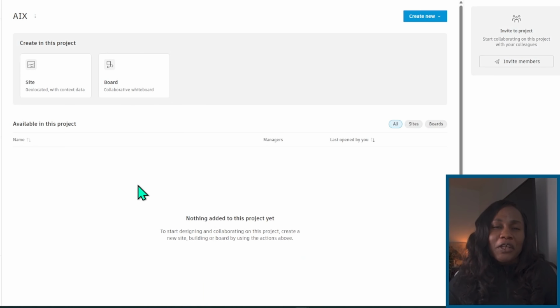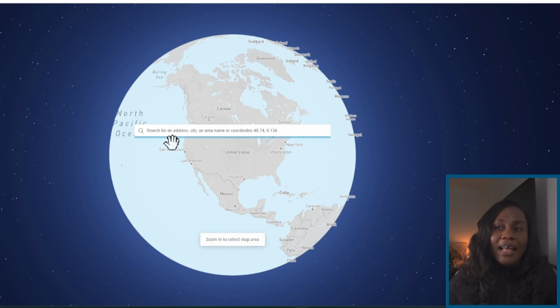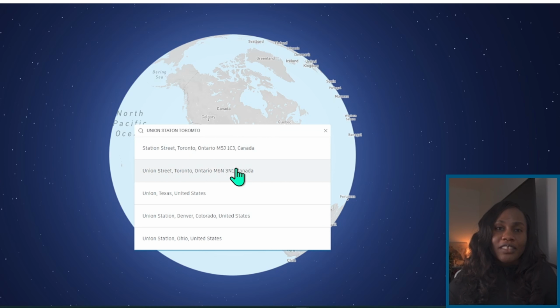Clicking on a newly created project that I made for this video, I'm able to create a board, like a whiteboard for collaboration, or create a site. For this video demonstration, I'll be using site. Now I'm asked to search for the address of the site that I would like to explore on Forma. A popular location in Toronto is Toronto's Union Station, so I will be putting Union Station to search for the location.